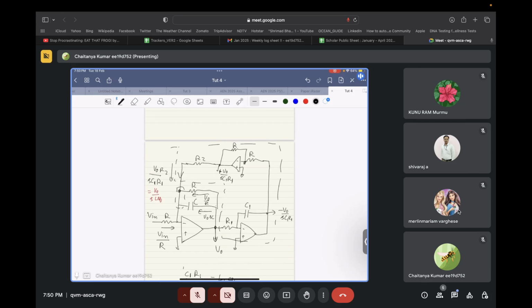Now this can easily be integrated on an IC. You might wonder that I have two resistances, two op amps, one capacitance and one resistance over here instead of that inductor. But to be very fair and to everyone's surprise, the area of all these devices that I have put over here will still be less than the inductor that you would need to put on the chip.